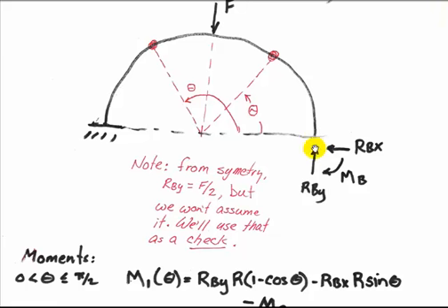Now, it turns out, because there really was a cantilevered end here, I know that the vertical deflection is 0. And I know that the horizontal deflection is 0. And I know that the slope angle from the cantilevered wall is also 0. So I'll write my deflections for each of these, and then set those deflections equal to 0, and then solve for each of these three unknown loads in terms of the load F and geometry.